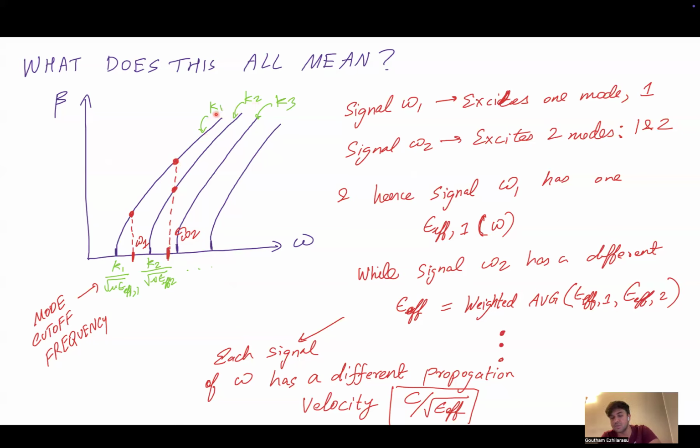And because each mode pattern has a different field configuration, the signal at omega 2 is going to behave very differently compared to the signal at omega 1, because it's going to have a very different time of flight. It's also going to change the matching configurations we had talked about in impedance matching. So this frequency change is going to cause a lot of issues for signal integrity.